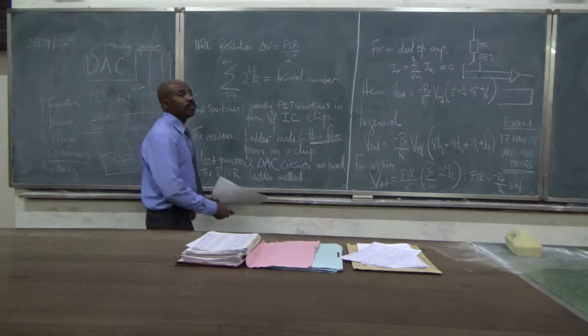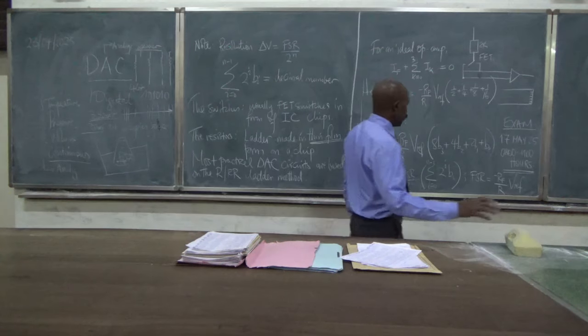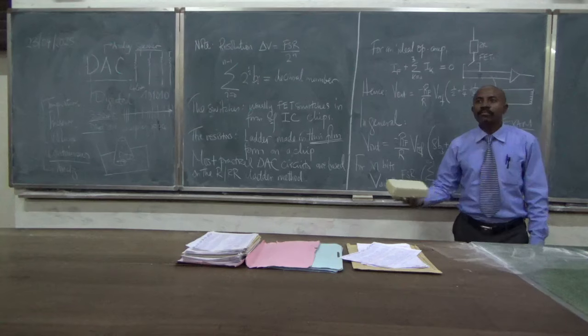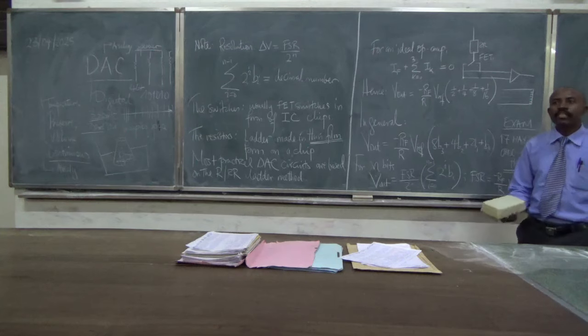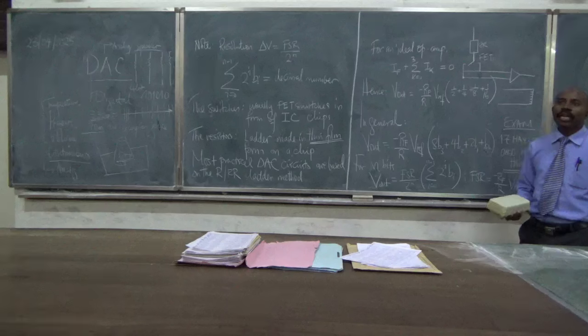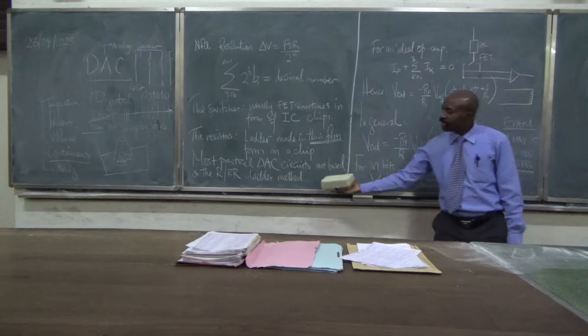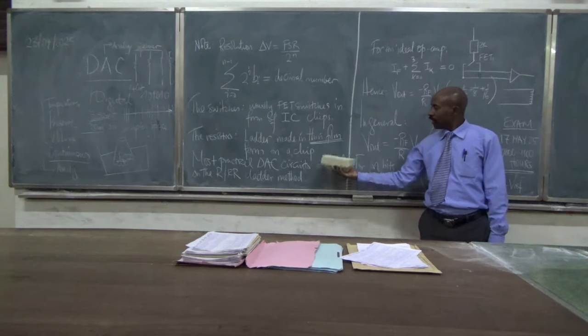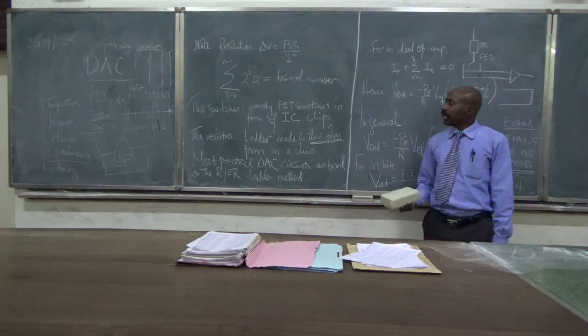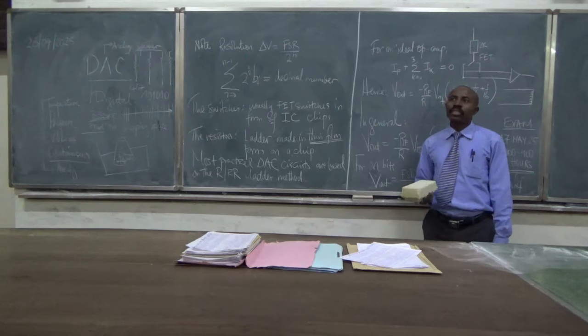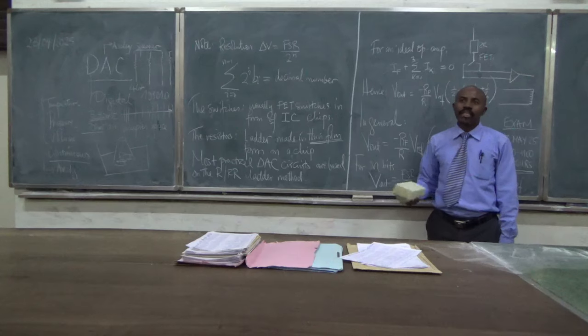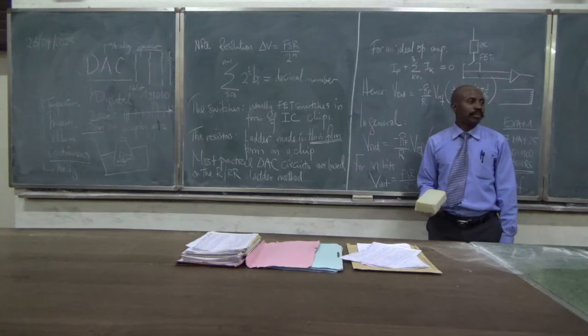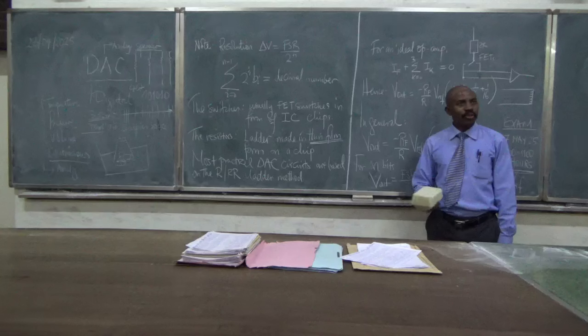So you will find most DACs using this method because of its simplicity. You just need one resistor duplicated in a ladder, and it can also be made easily in the form of a thin film. And then the switches are made into FETs, which are just a bunch of chips. And then everything is automated.